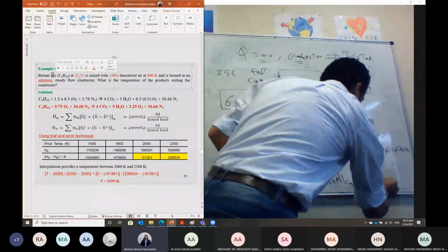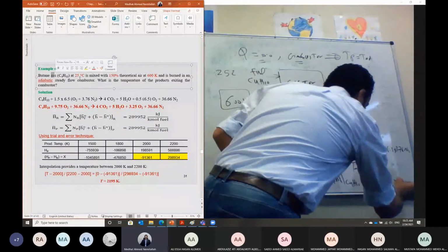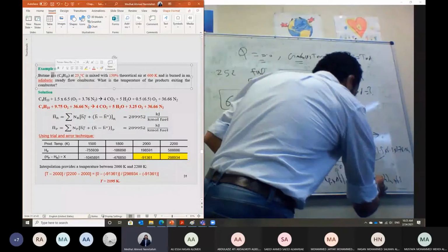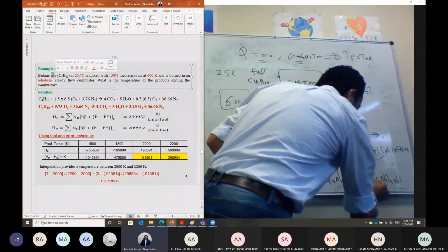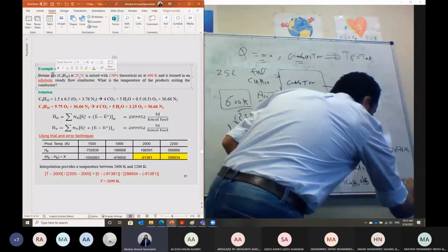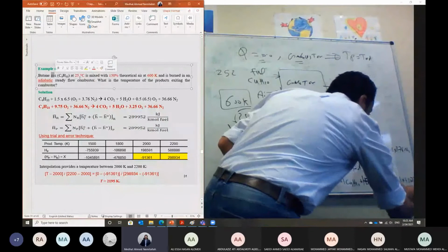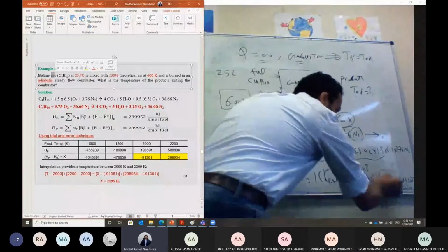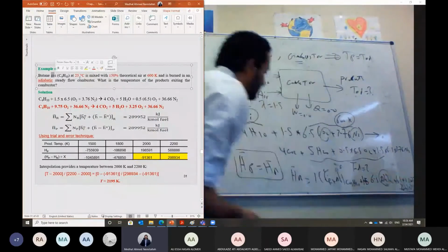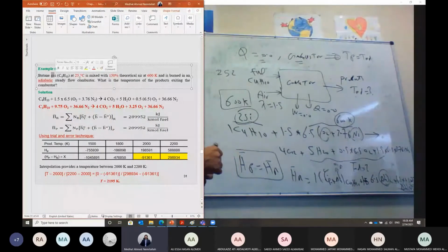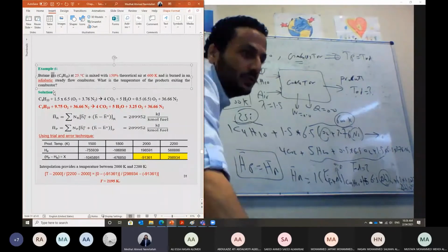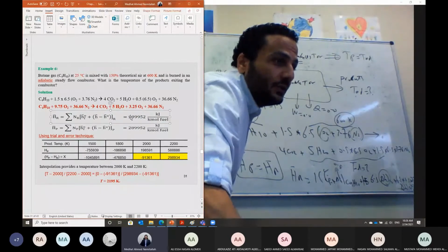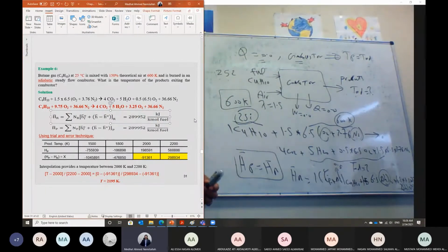So it will be plus 6.5 delta H of O2, plus 1.5 multiplied by 6.5 multiplied by 3.76 delta H of nitrogen. Those delta H values for the O2 and the nitrogen, we can just get from table A3. Okay, if I substitute, I will find in this case, guys, that the enthalpy of the reactant will equal this number. So let's write it down.